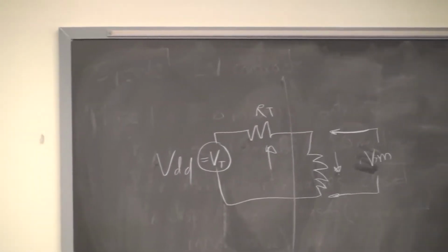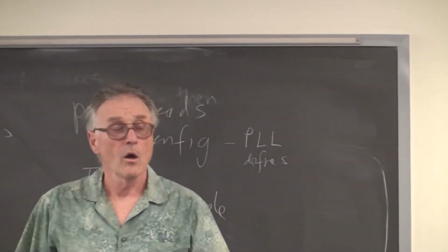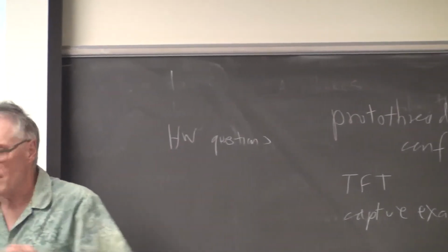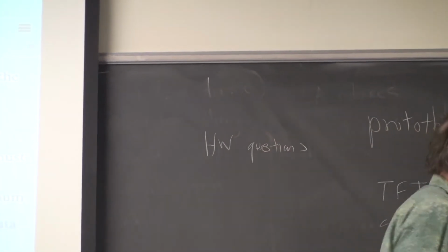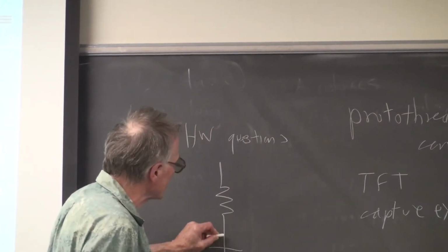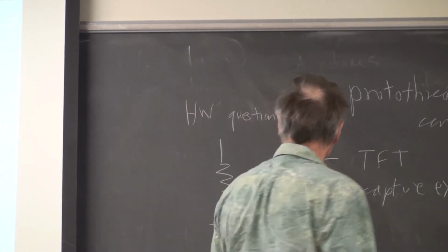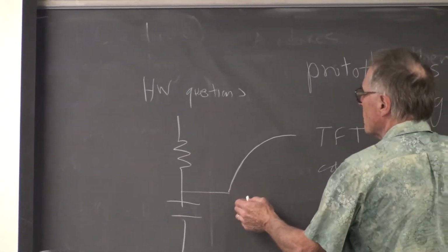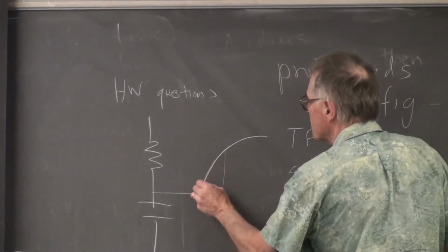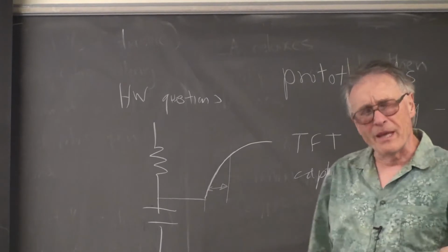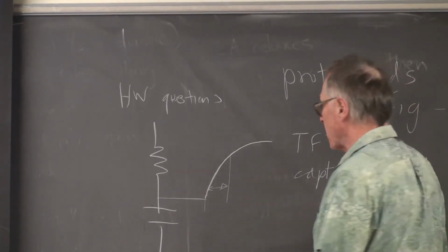Any more questions on homework? Yes? How do you choose the prescaler? Oh, well, yes, prescaler for the timer. So what you're trying to do is measure the time constant of some circuit that's charging up after a square wave is applied to this circuit. And what you want is the charging time with a minimum, but you're making the measurement digitally with a counter.